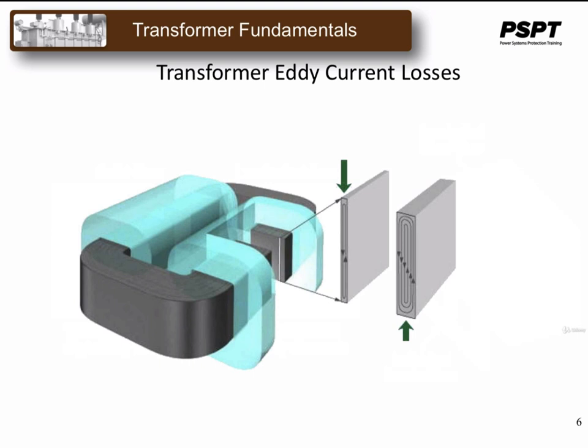These laminations are insulated from each other by a coat of varnish to increase the effective resistivity of the core, thereby increasing the overall resistance to limit the flow of eddy currents. The result of all this insulation is that the unwanted induced eddy current power loss in a core is greatly reduced, and it is for this reason why magnetic iron circuits of every transformer and other electromagnetic machines are all laminated. Using laminations in transformer construction reduces eddy current losses.